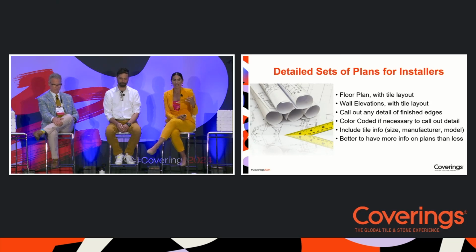And then calling out any detail on the finished edges. So in those elevations, if you're using a finished edge on the piece, if you're mitering that edge, all of this stuff really needs to be detailed. You never want to leave it up to chance. You want the installer to have as much information as possible.